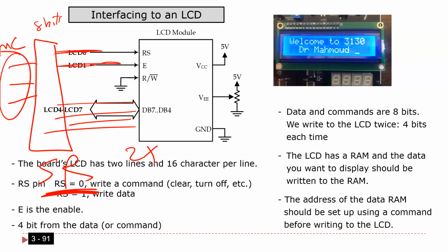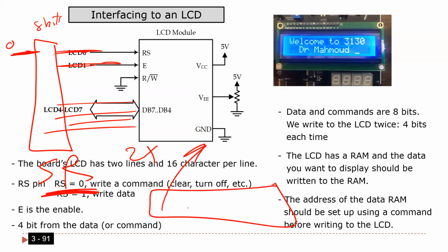Okay, guys, so now this is how it is. The microcontroller is going to be connected to the shift register, and the shift register is going to be connected to the LCD. For this shift register, you need only 3 pins. You need 1 pin for the bit you want to enter. For example, if you have a byte, you have to take bit by bit. You have to send bit by bit. That's why it's slower. You got what I'm saying?